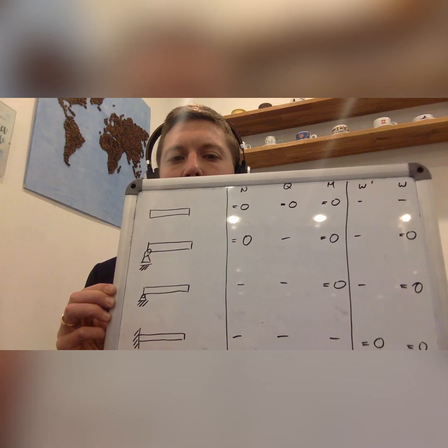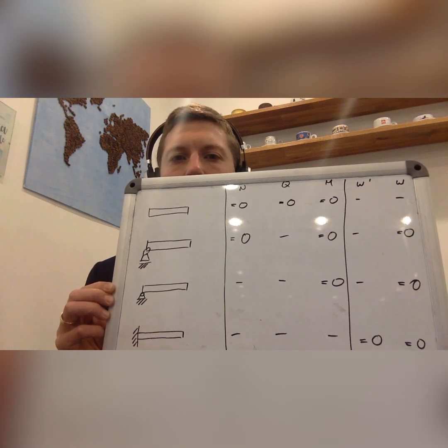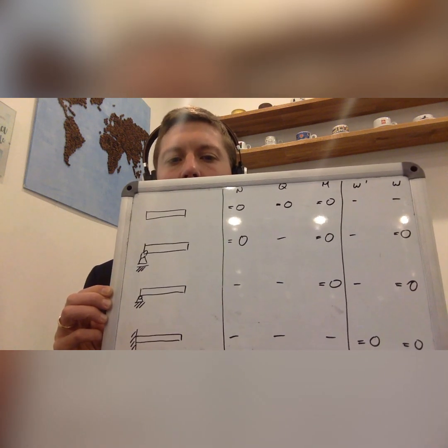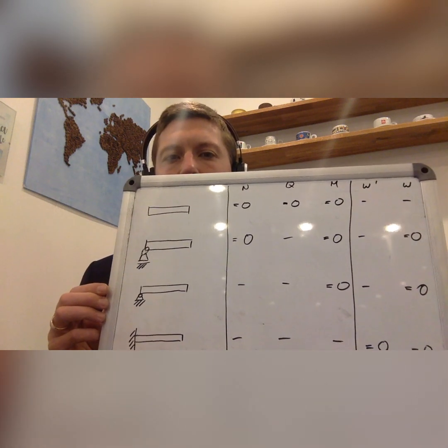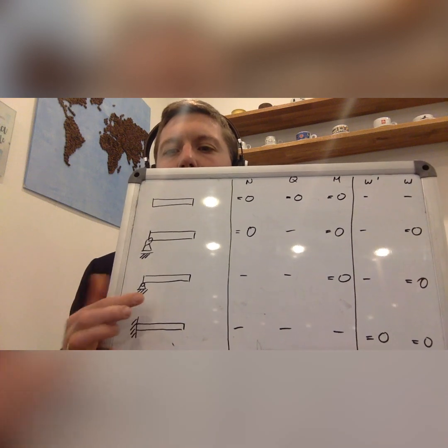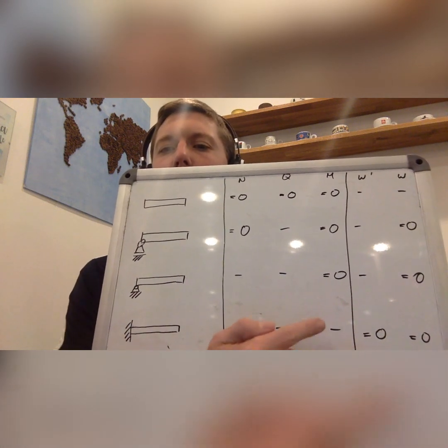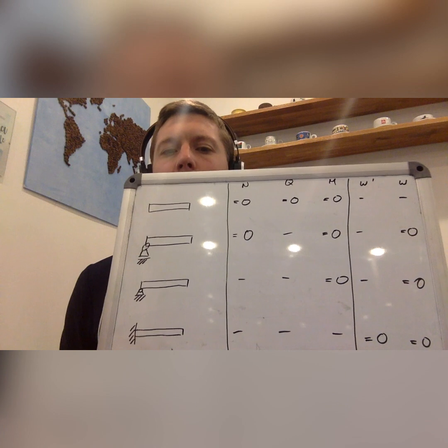In this case, we would have an inclination of 90 degrees, and this would not change if you apply a force here. So that means, out of this definition of the fixed bearing, not only this w equals 0, but also this w prime equals 0.